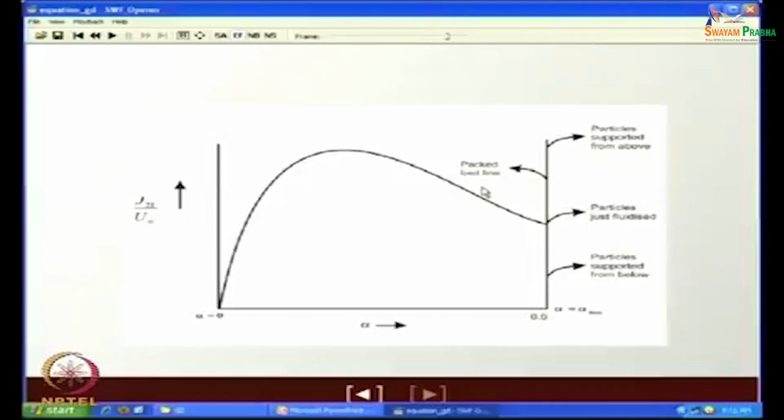So, this is one particular point which I wanted you to remember: for gas solid cases, since they are very flexible, the curve can extend from alpha equal to 0 to alpha equal to 1. But for fluid particle cases, they cannot extend beyond the critical value of alpha, which gives you the maximum limit of solid packing. Beyond that, solid-solid interactions become important, and the basic assumptions based on which I had made the derivation are no longer valid. Okay? So, beyond that we cannot proceed.